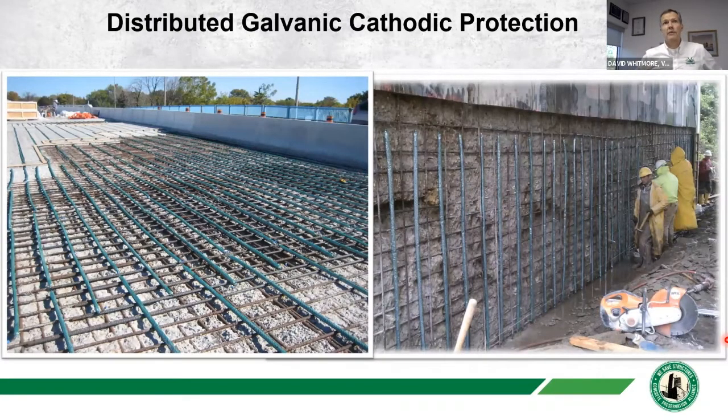Could be like either of these examples that you see here, but here the intent is generally more to provide full cathodic protection, galvanic cathodic protection to the whole element, a deck as illustrated on the left or a substructure on the right. For that, you're basically going to use the same principles that we're going to talk about, but you're going to use higher current densities and higher, obviously, polarization parameters if you're talking about cathodic protection criteria.